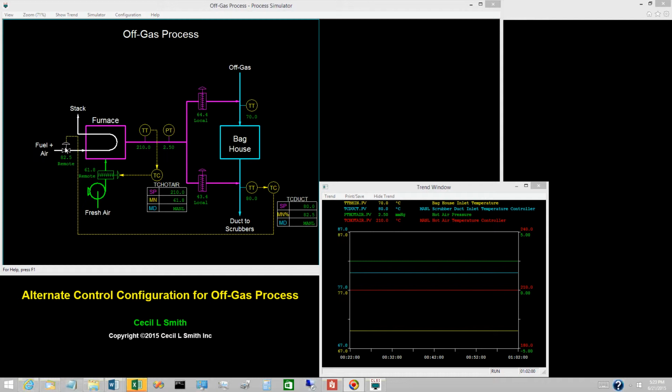The control each variable with the nearest valve philosophy suggests that this valve is too far away for effective control. The hot air damper to scrubber duct inlet affects the scrubber duct inlet temperature more rapidly, but the effect is only temporary. We should use a final control element that causes the process to do what is required without relying heavily on the other loops. For controlling the scrubber duct inlet temperature, that final control element is the fuel gas valve.